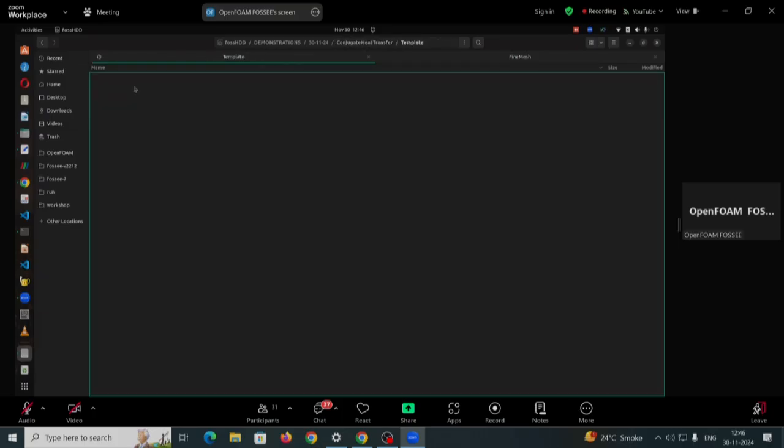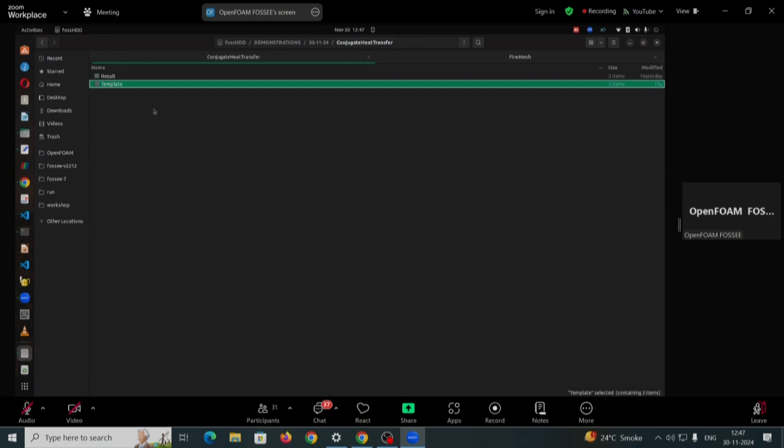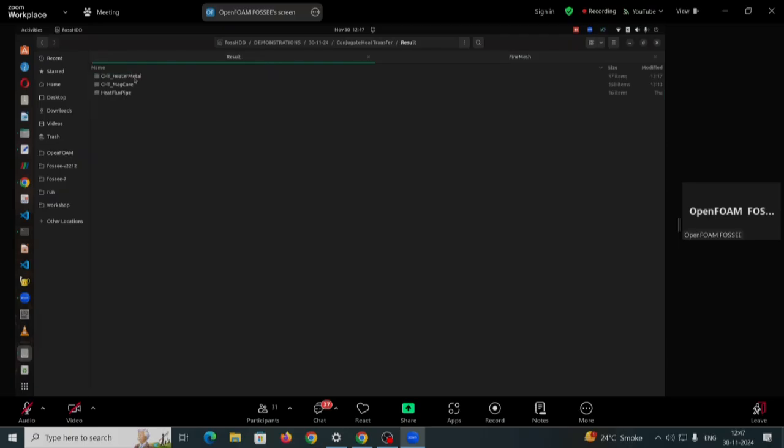Okay, yeah. So in the template we have 3 files. Similarly, we have for multi-phase and dynamic meshing as well. Yeah. So let me go to the result and directly present. Running buoyantSimpleFoam is pretty straightforward. You just run blockMesh and then you run the buoyantSimpleFoam case.